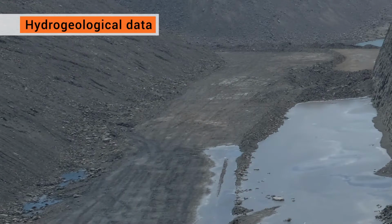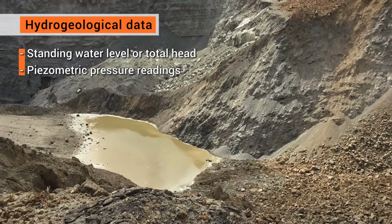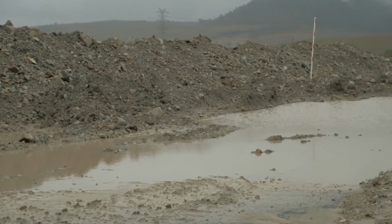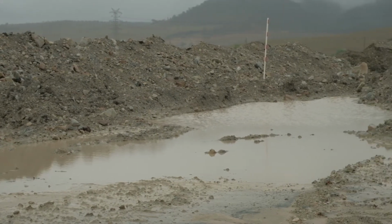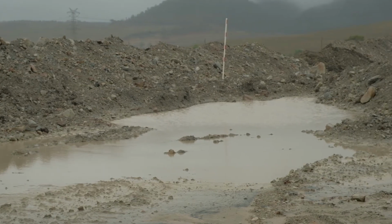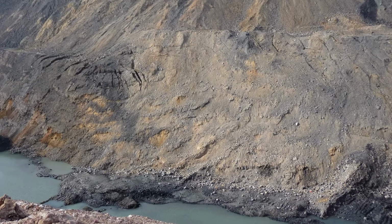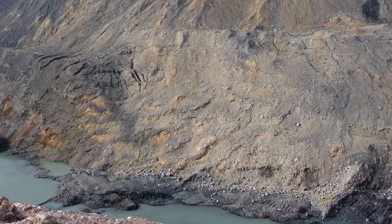Hydrogeological data required includes standing water level or total head, piezometric pressure readings, and hydraulic conductivity and flow rates. The degree of saturation, seepage, groundwater flow, or build-up of pressure or depressurization behind a slope face can have a significant effect on excavated and dumped slope stability.